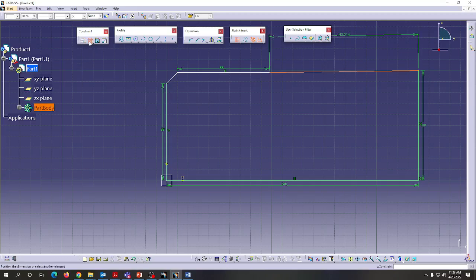For that I'm using the constraint toolbar again. I don't want this one. I'm clicking constraint. So this horizontal line and this point, this one I require, and again I'm clicking this point and this horizontal line, because I'm giving the same constraint, it is coming over here. I'll explain why it is coming in another color. This vertical point, this horizontal line. This is for the horizontal distance for the particular slanting line, and this is for the vertical distance. So like this I have given the dimension.